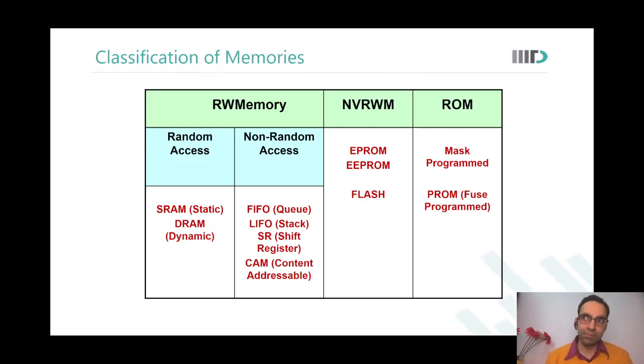Programmable ROM means, for example, let us say there is some part of the system which is failing. You want to disable it, or you want to send a little higher voltage to it so that it starts to work. Since this part is already failing, or you suspect that it would fail in the field, you calibrate the system in such a way that this chip would generate a higher voltage than regular. These PROMs are fuse based, and they are typically used for calibrating the system so that it operates at an optimum voltage or frequency or throughput.